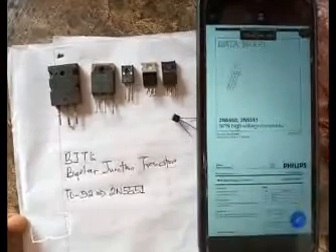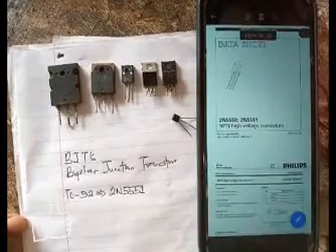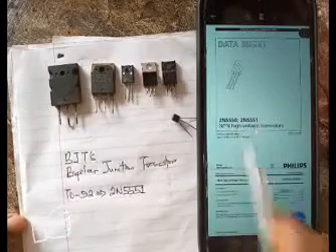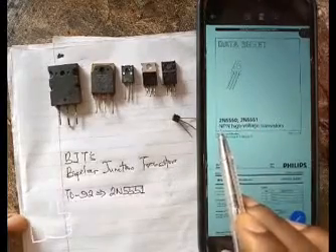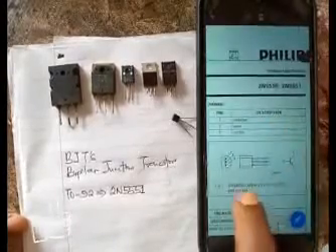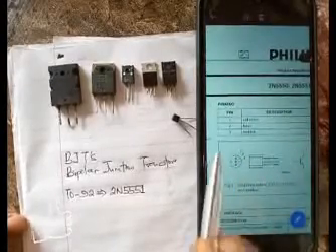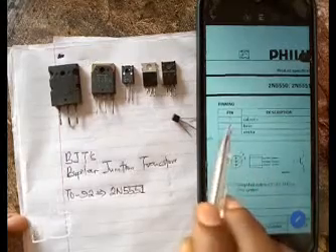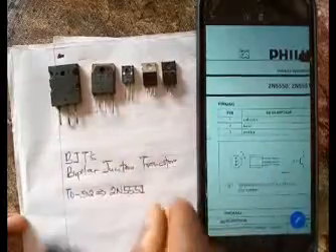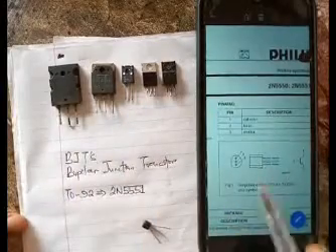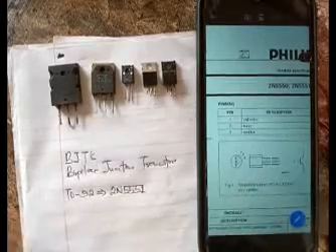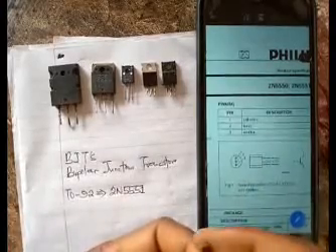So this is a data sheet that gives us a lot of information about this particular transistor. You see that the number is written there, and it tells us that it's an NPN transistor. Then if we come down to look at this part, it tells us the pinouts, that pin 1 is the collector, and where is pin 1 here? This tells you that if you are looking at the transistor from the base, meaning that there's a curved part here.